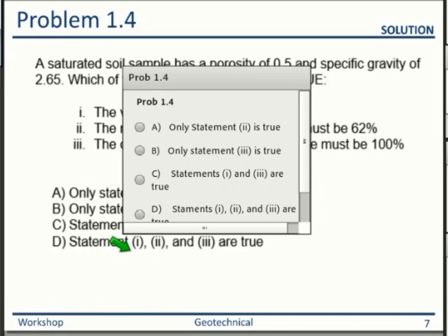Yes, Patrick, we're not adding any soil, we're adding water, right? The moisture content equation, weight of water divided by weight of soil solid, that you have written is moisture content. So you have to make that moisture content increase from 20% to 30%. All right. So how do you show that increment? The increment is shown as we went through in problem 1.3. Okay.